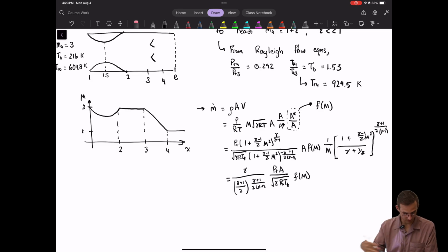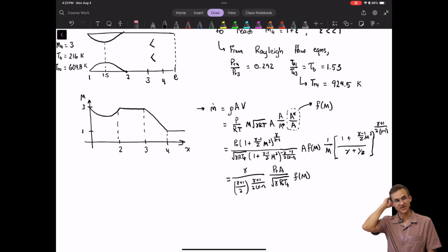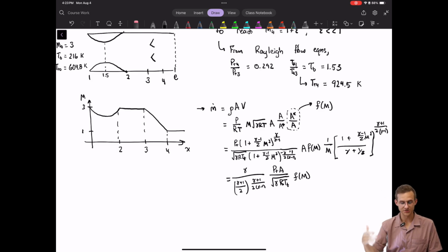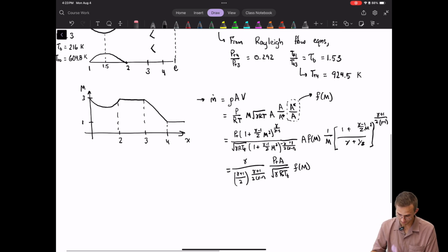You will do this over and over and over again. At any point in your homework, whenever you're analyzing these systems, one of the first things that you should try when you really get down to doing some algebra and math is to equate the mass flow rate between two stations, as long as there's not some sort of fuel injection happening between the two stations. In which case, you'll often be given the fuel mass rate, or you might solve for or be given the difference between the flow rate of the fuel mass and the air mass in the engine.